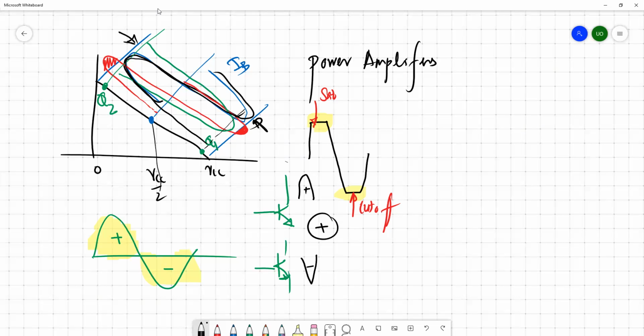So once you get that idea, you can easily design a transistor amplifier, because if you set up or finalize the Q point and place these resistors and capacitors in the circuit, and you plug in the input and get a distorted output, you know whether you have to move your Q point in the cutoff direction or the saturation direction, depending on the half cycle in which the clipping has happened.